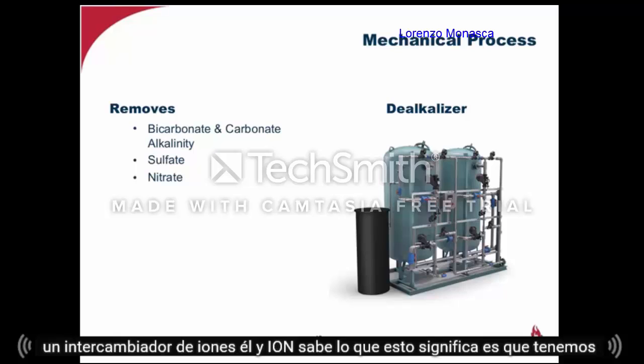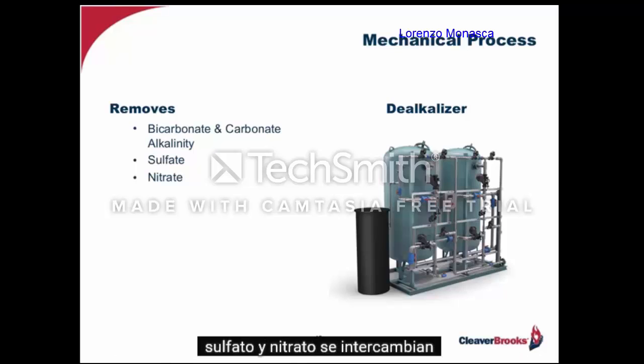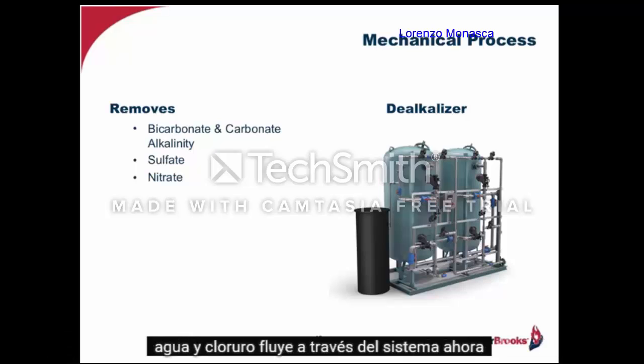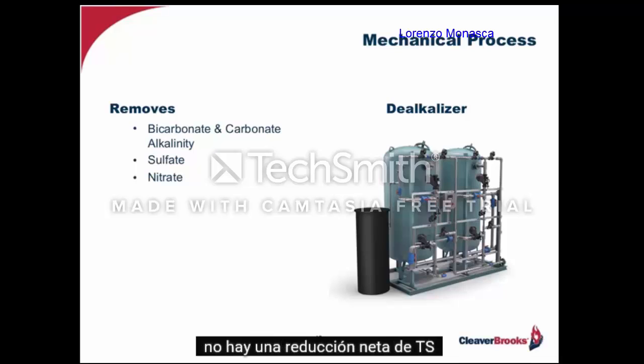Now, what this means is we have specially engineered resin beads in the dealkalizing tank, which also allow a reversible transfer of ions. Then the stronger alkalinity ions, carbonates and bicarbonates, sulfate and nitrates, are exchanged for weaker chloride ions, resulting in dealkalized water and chlorides flowing through to the system. Now, since chloride replaces each of the ions that you remove, there is no net reduction in TDS.